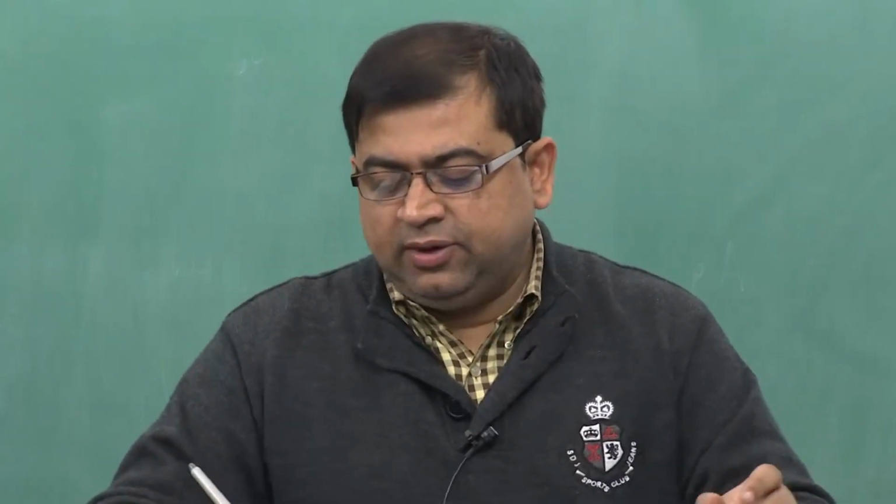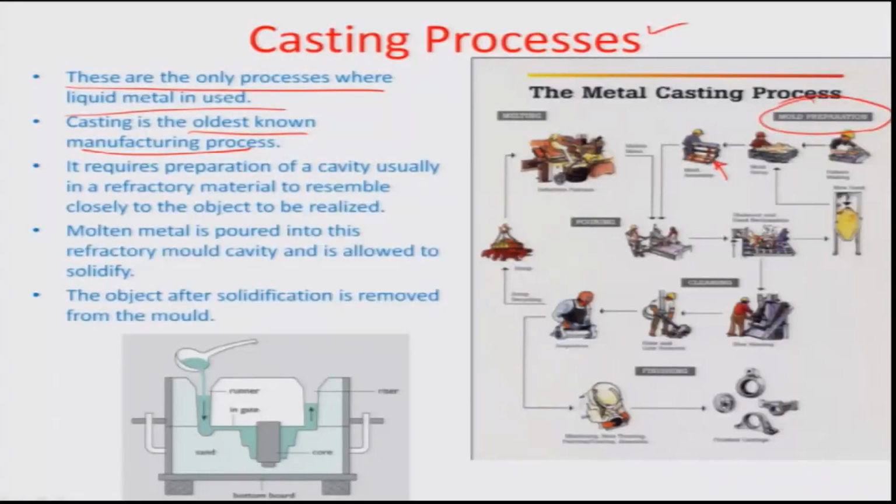So what you do is that you have a flask set which is shown right here, and also you can see this is the assembled view of the whole mold with the different flask sets, and you have different layers each containing one flask, and the flask therein containing refractory material. So you start with such a flask. This is one flask, for example, where you are actually pouring the refractory material, sand, and setting up the mold.